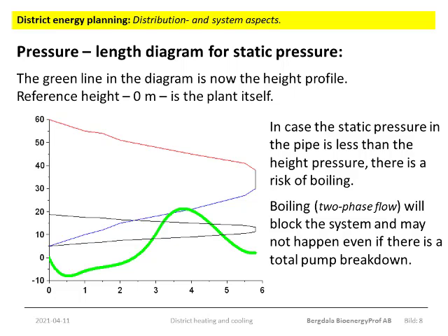Now will you understand why we use meters as the measure for pressure, meters of water column? Because now we can add the terrain curve in the same diagram as we have the pressures, and that is the thick green line. In Lima we had a terrain height curve starting at 113 meters, peaking at 160 and then dropping off again with a few depressions along the way. In the slide we start at 0. There is a depression and a hill, and then it drops off again.